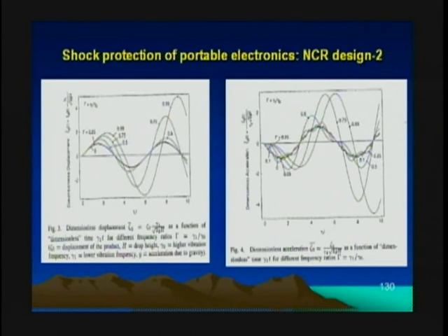So we simply don't want to have a situation when this vulnerable element goes down, and the cabinet sticks to the floor, and the chassis goes back, and we end up with something like that. That's certainly the worst thing to have. And this corresponds to the resonant conditions between 2 frequencies. So if these 2 frequencies are close to each other, that's certainly the situation that we want to avoid. And what you see here is that if the ratio is 0.9, the displacements become huge, the dimensionless displacements and amplitudes on the right become huge. At the same time, if this frequency ratio is only 0.5, you're in good shape, so the vibrations do not increase, do not accelerate.